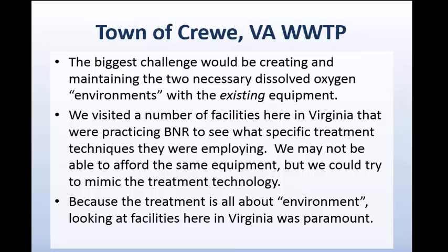At the time that we took this project on and we were coming into compliance with total nitrogen limits, we were exclusively a one environment treatment plant or one habitat, and that was abundant free dissolved oxygen throughout.